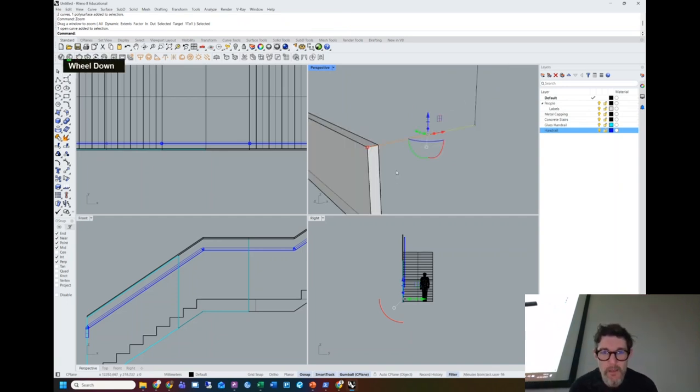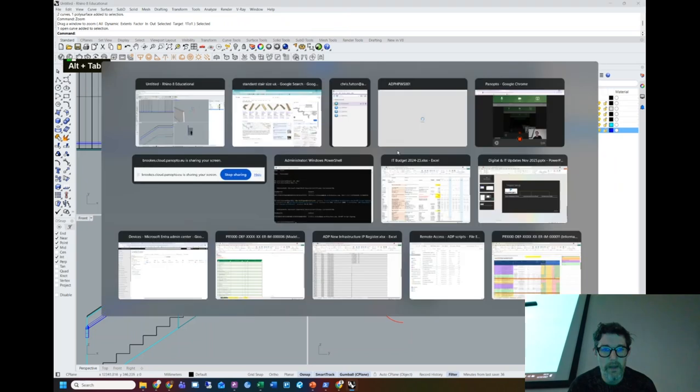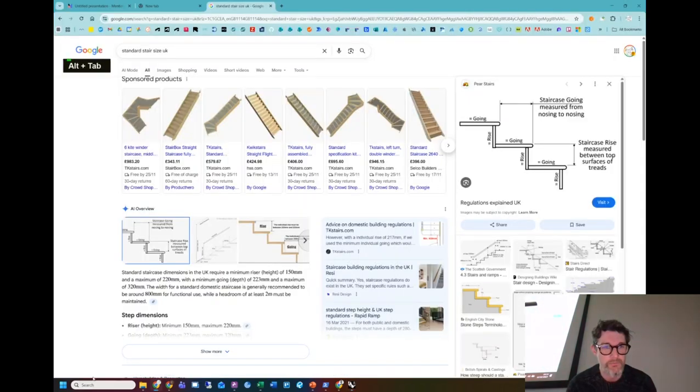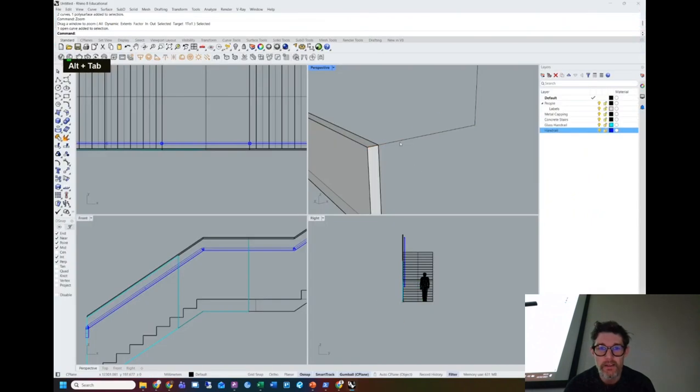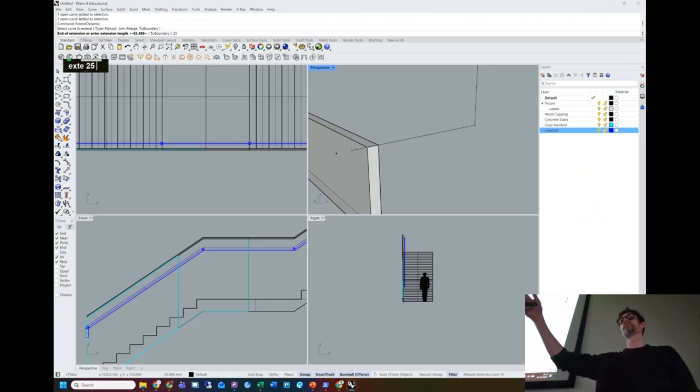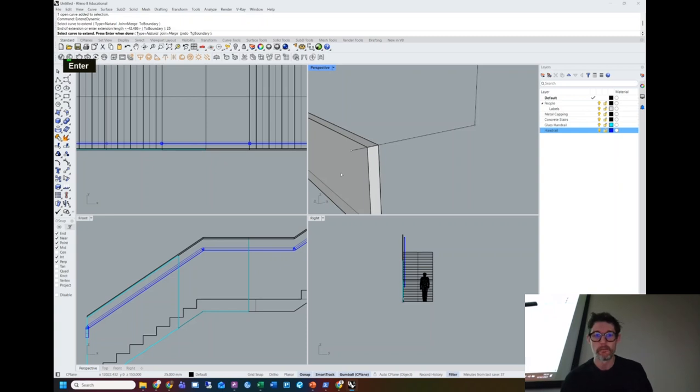Cool. The nice thing about timber staircases, let's head back to our drawing of a staircase. There's something called a nosing. Do you see this? It's like the stair actually carries on a little bit further than the edge. And we can model this. We can take this line, extend dynamic. I'm going to keep it going, and I'm actually going to type in, I want a 25 millimeter nosing. So I'm extending it 25 millimeters beyond where it was before. So I just type 25, press go.